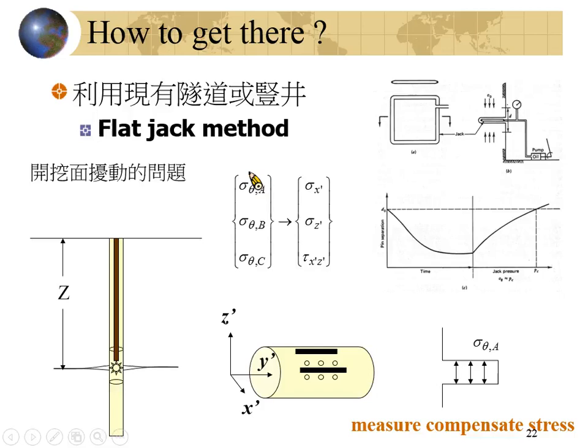There are two important influences for the tunnel wall excavation. One will be the excavation technology. You could try to use the drilling and blasting, D&B method, to excavate the tunnel. Drilling the borehole and putting in the dynamite and exploding it and trying to remove the rocks.